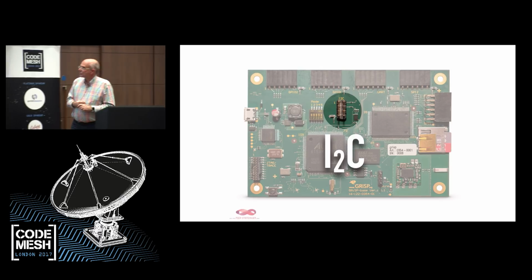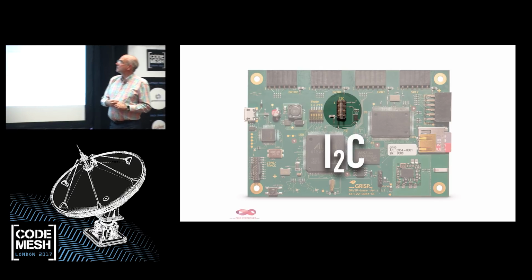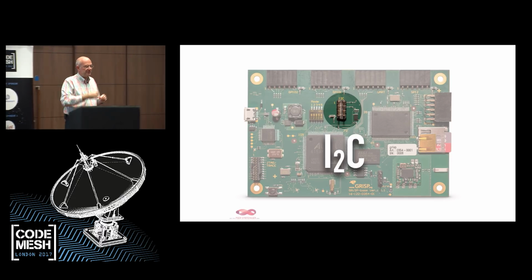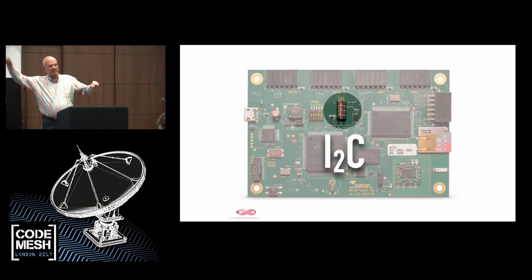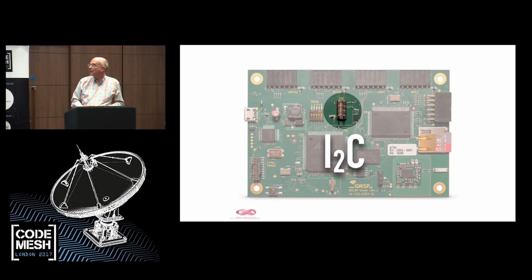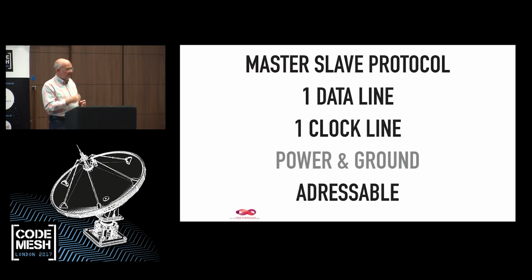The I2C is actually in the middle of the board, here in this little circle, because I2C is a bus, and normally you have these ribbon cables where you can have multiple I/O things on one I2C and you plug them in a chain. I2C is similar to SPI, but different. It has only one data line, and the clock line stays the same.